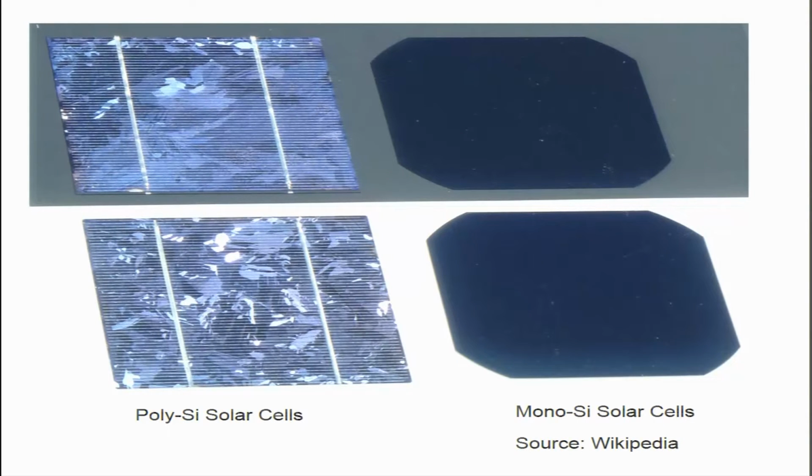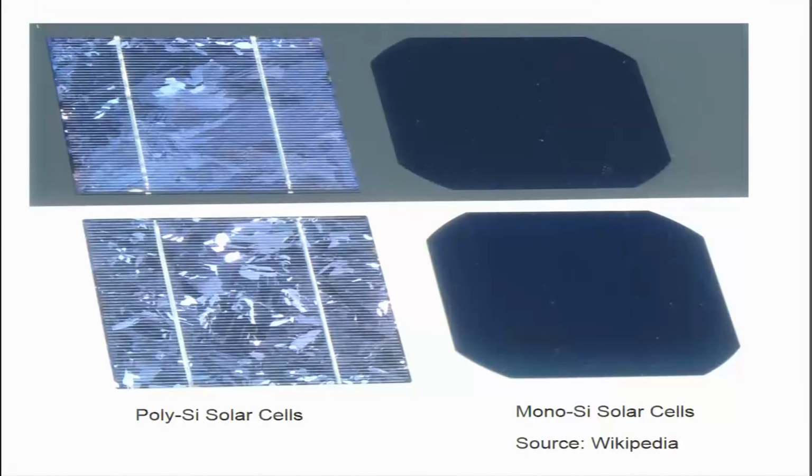If you look at the polysilicon, because you have grains of different orientation on the surface, different grains have different reflectivity. There is a surface texture, and you can see this blue, white, black kind of texture on the surface. So, on the left you have two images which show you the texture of a polycrystalline silicon, which is very different to monocrystalline silicon. So, this is a distinct difference between the two solar cells, two wafers, from the perspective of distinguishing them.